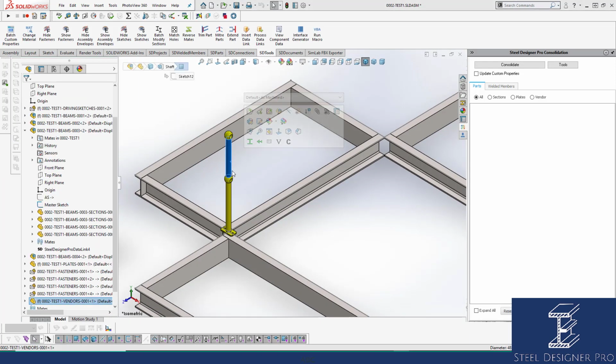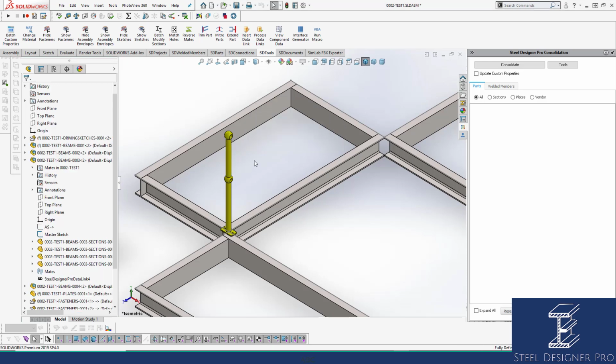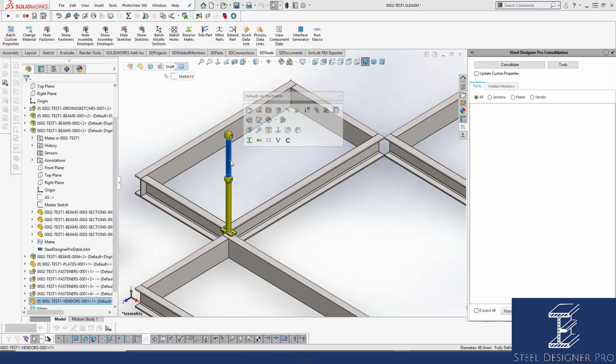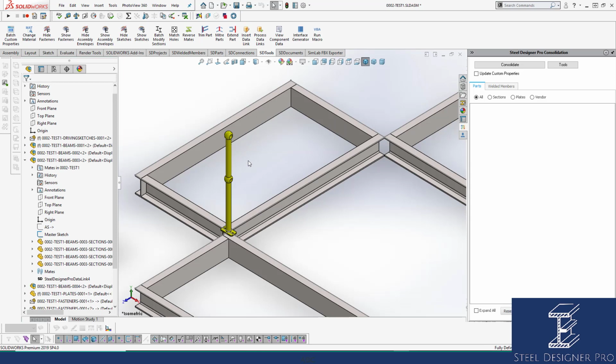Make sure that your vendor items have their data in them so that when you do add them to the library, the data doesn't have to be put in them after, which can be dangerous because when you go to insert your vendor items over and over again, then the data will have to be added to all of those components. So just make sure that your vendor item has all of its data before it goes into the library. And if it does go into the library and it's missing the data, I would suggest you open it up in the library and fix it straight away.